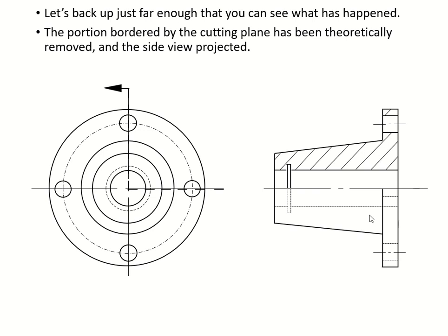Since we didn't cut, they are still hidden lines. The bottom part is going to be, and this is completely hollow because you have a hole right here. Because you also have a little exposed area here. This is going into here, so there's only one line, so don't forget they are equally spaced from one line to another, your crosshatch lines, and of course at about 45, 30 or 60 degrees from the horizontal line.